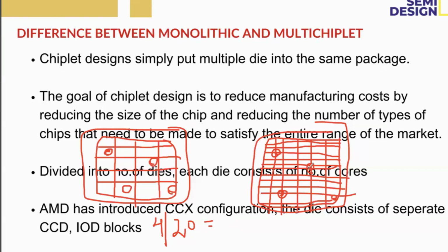So here the number of defects may be some 40 and the number of blocks will be 100, then 40 by 100. So the percentage will be higher here and lower there. So yield will be high, so that whenever we have defects, the entire chip is not affected. So it is easy to detect the defects and to go for debugging.